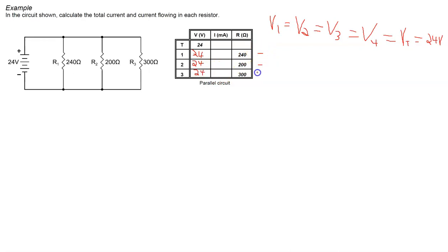And so we could start this one by applying Ohm's law to each resistor individually. Now, typically we can't start a series circuit like that, but these parallel circuits we can. Okay, and so we could start off then by finding the current in each resistor and then use Kirchhoff's current law to find IT, couldn't we?